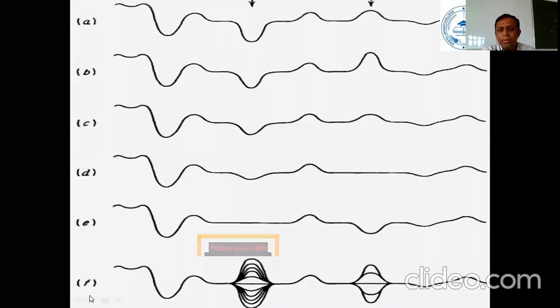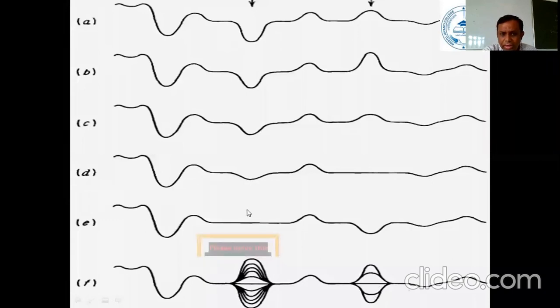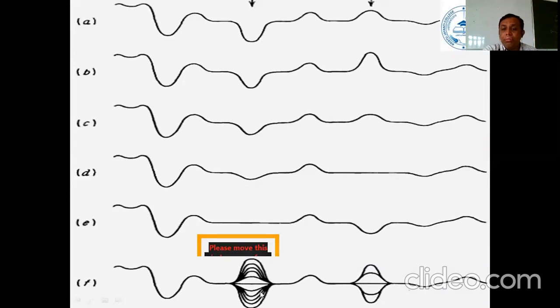Now this is given to a subtractor. The subtractor identifies that there is a difference between the pulse I have received and the pulse I am receiving after 1 by PRF. This particular difference is given to the subtractor. The output of the subtractor will give a number, and that number will give you the velocity of the moving target. I said that the output of this radar will be only one number, and that number is the velocity of a moving target.